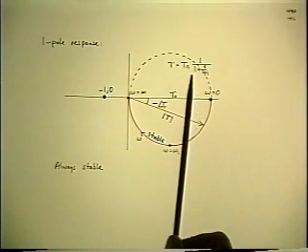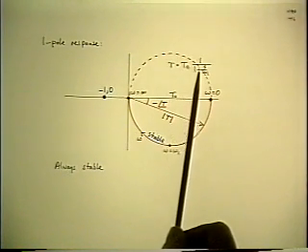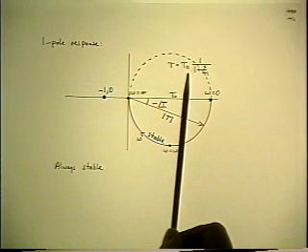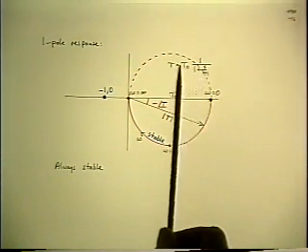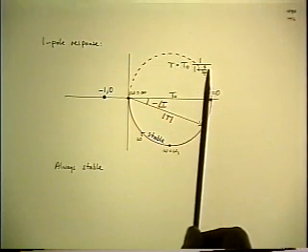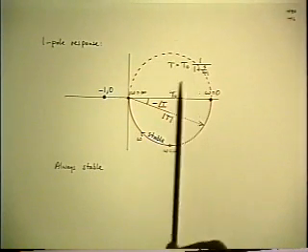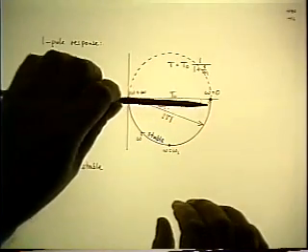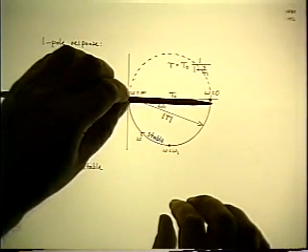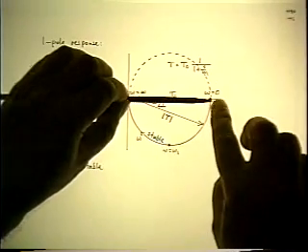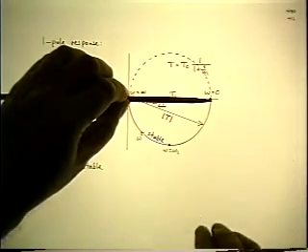Let's take the simplest form of loop gain, which is a flat value t0 and a single pole. The way you make the polar plot is you start with 0 frequency, t equals t0, so you draw a phasor length t0 at 0 degrees to the reference direction. You label the end of it omega equals 0.